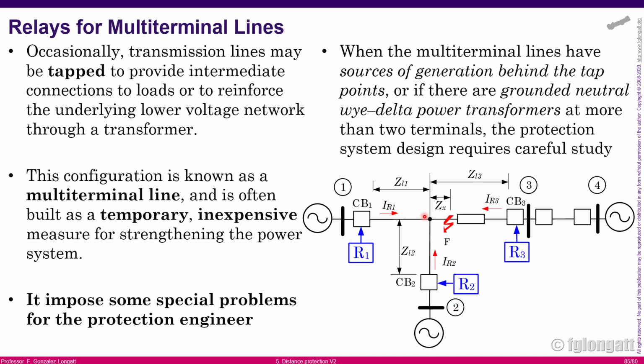In that case, we have three terminals. We have three terminals for this configuration. You can see a T over there, or a star connection if you wish, but that is what is happening. We use the name multi-terminal for that. We do not use that for extra high voltage. In extra high voltage, we will never take the risk to do that, or if we do it, it will be for a very important reason. However, in high voltage, it is probable that this can happen.